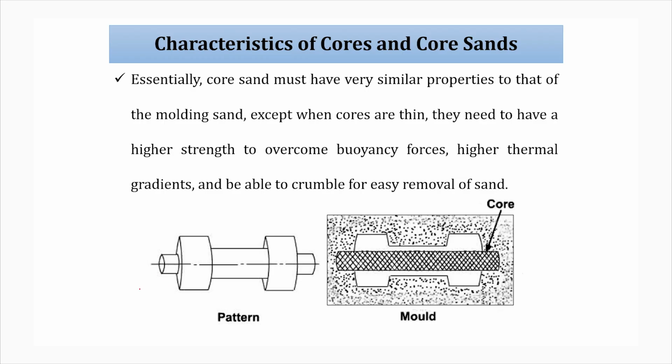I want a hollow feature. So, this is the core and this is our product, and the product with some allowances. The product already has allowances, like shrinkage allowance, machining allowance, and draft allowance. You can see draft allowance is already given to this pattern design. And in the pattern you can see extra features. This I don't need in the product. I need only this, and this, which is hollow.